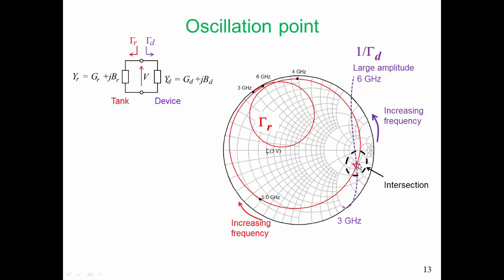And we see this in many of our oscillators. Of course, the oscillators that don't have this behavior are simply not used anymore. So it would be possible to have an oscillator that goes into a chaotic state at that point. But the oscillator topologies that we have come to adopt have this characteristic where that small variation in the harmonic content locks us in on that frequency of oscillation.